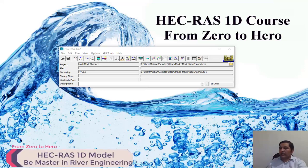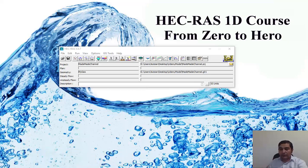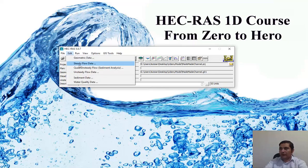Okay, after defining the location of geometric and shape of them, we should enter the flow simulation and set boundary condition. You know, HEC-RAS is a numerical model and requires boundary condition values to start simulation. For entering flow values, you should go to Edit menu and select Steady Flow Data.